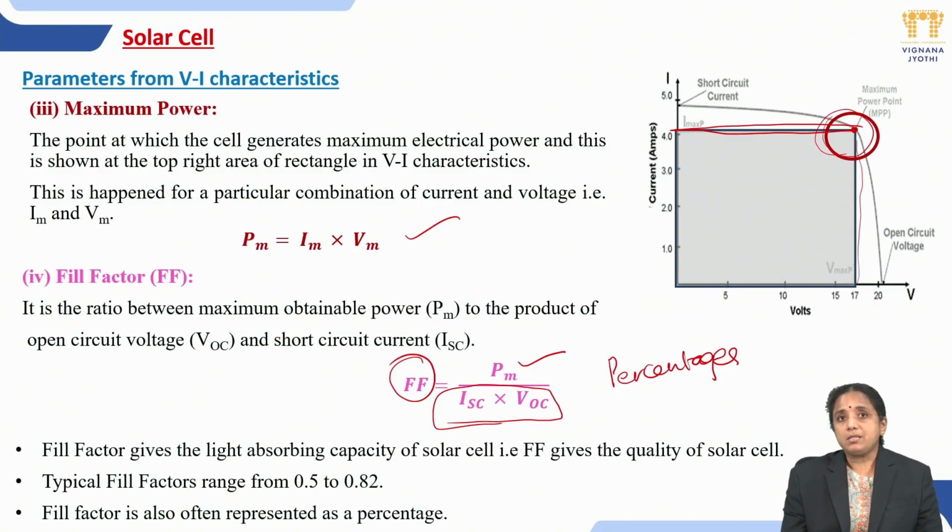In the case of solar cells, we have to see that the materials, as P and N type materials, have light collecting capacity. In the case of LED, we have to see that more charges are accumulated across the junction within a short time and recombinations are taking place. So these are the basic differences which we should consider while fabricating light emitting diodes or solar cells by using PN junction diodes or by using the P and N type materials.